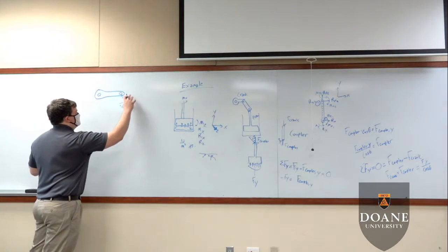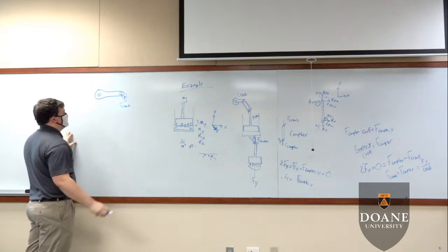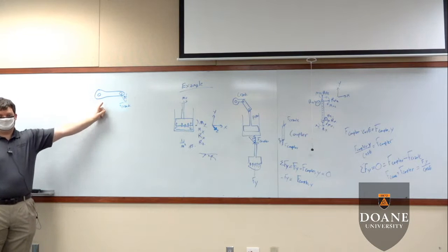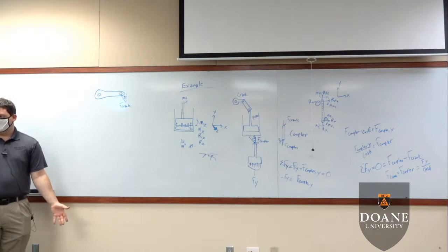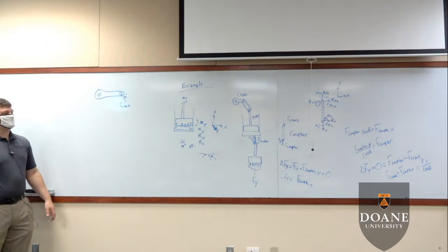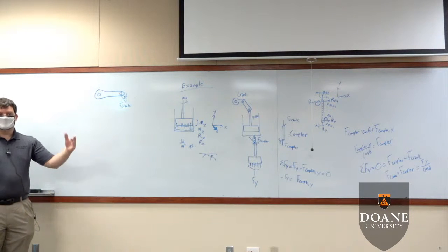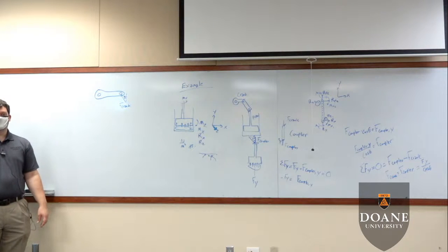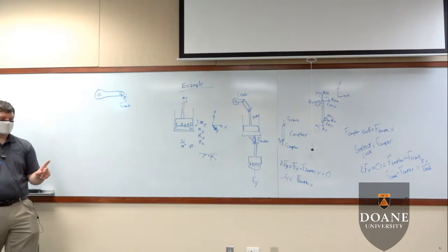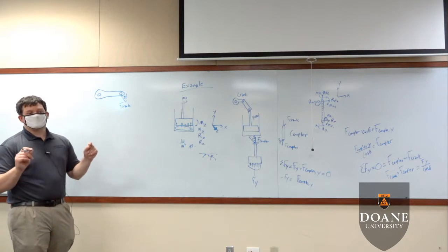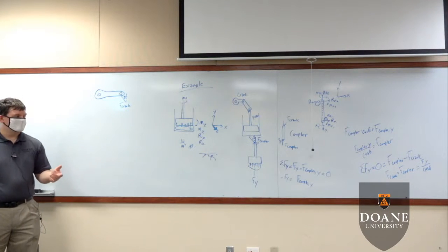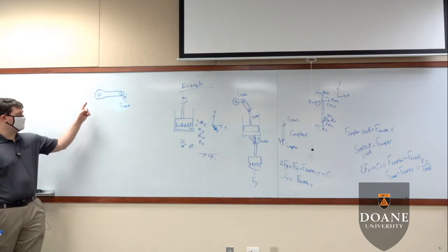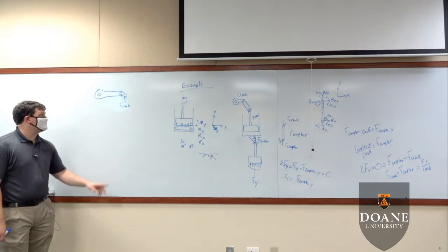This perpendicular component right here is going to create a torque about this axle. It has to. So if we just treat this like a revolute joint, our math is now blown. We have to recognize it's going to accelerate, or we have to recognize there's an output torque. The output of this system is a torque. There is a torque being exerted on this pin.